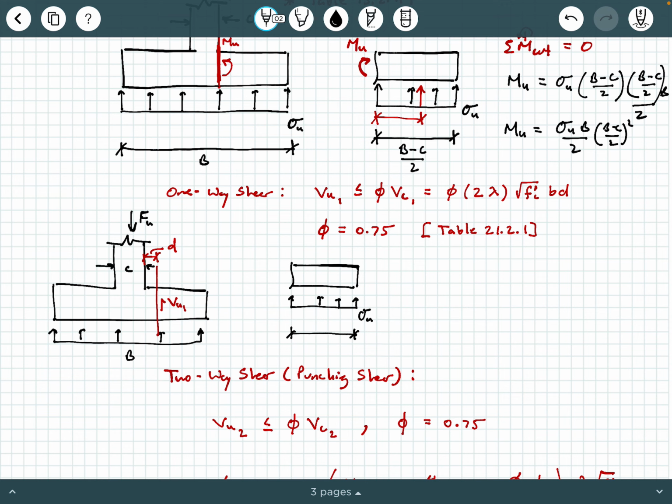So how do I get this dimension here? Well, similar to what I did before, I just measure things out, but I also subtract out a d value. So what I'm looking for is this length right here, this horizontal length. So I'm going to say B over 2 minus C over 2 minus d. Or you could repackage that as (B minus C) over 2 minus d. And that's what this dimension line is here.